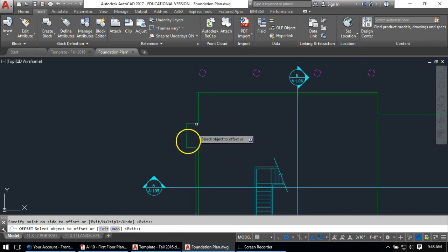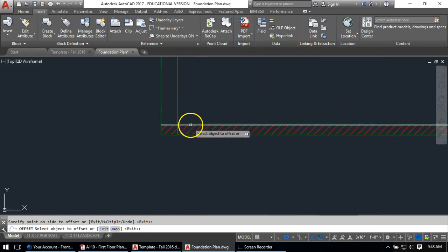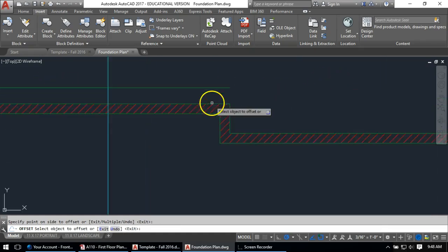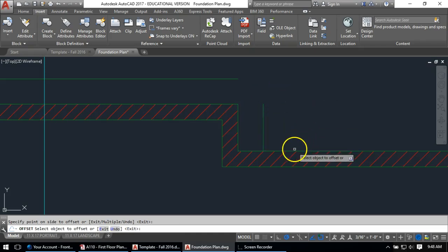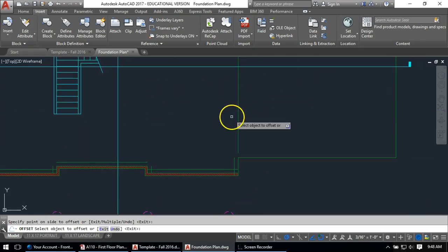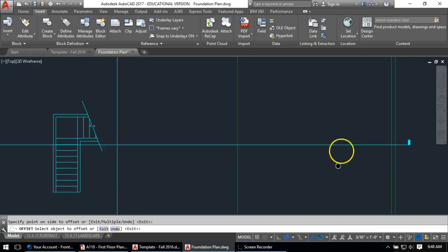The fireplace itself is going to be drawn sort of differently, and I think I'm going to actually draw it a little differently than shown in the plan, because it looks like in the plan there's a stud wall that goes around the fireplace, and I don't think that's correct. So we'll come back and I'll show you that in the video. If you happen to draw it like you see it in the drawing, I won't mark off for that, since you know, not everyone's necessarily following the videos intensely. And the garage width being that it's also just going to be a stud wall, probably with drywall.